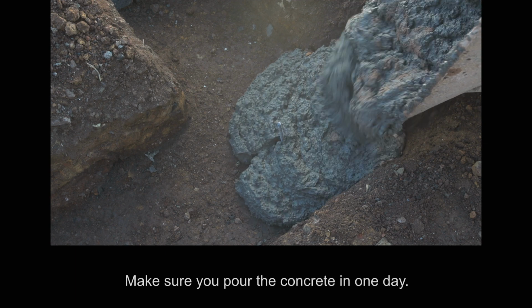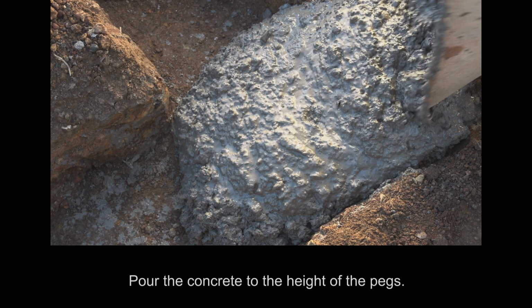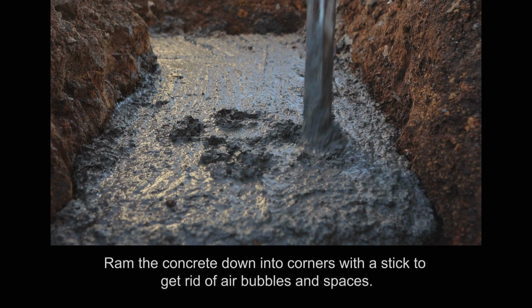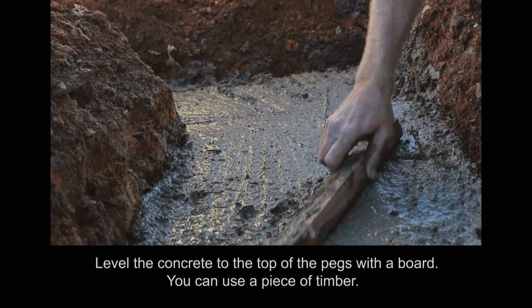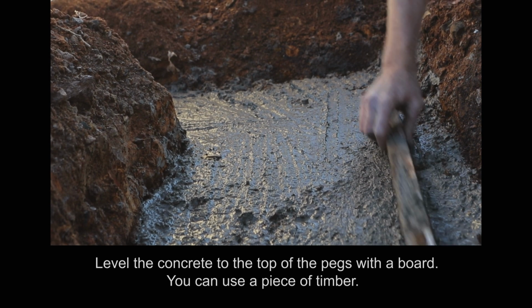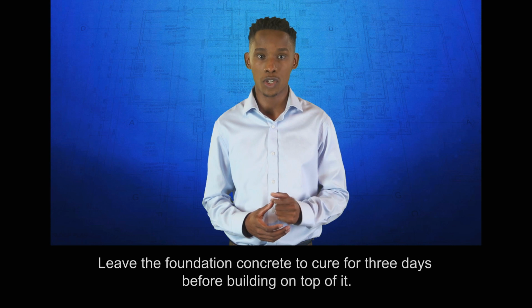Make sure you pour the concrete in one day. Pour the concrete to the height of the pegs. Ram the concrete down into corners with a stick to get rid of air bubbles and spaces. Level the concrete to the top of the pegs with a board. You can use a piece of timber. Leave the foundation concrete to cure for 3 days before building on top of it.